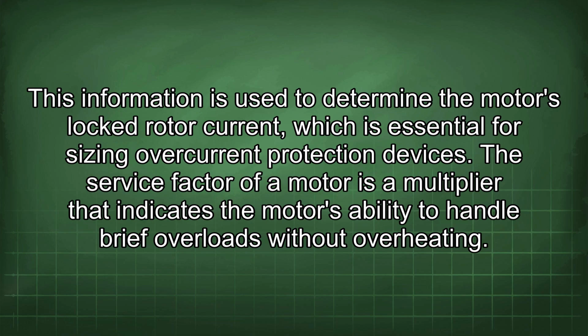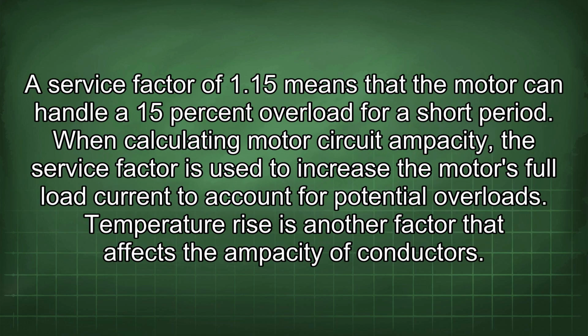The service factor of a motor is a multiplier that indicates the motor's ability to handle brief overloads without overheating. A service factor of 1.15 means that the motor can handle a 15% overload for a short period. When calculating motor circuit ampacity, the service factor is used to increase the motor's full load current to account for potential overloads.